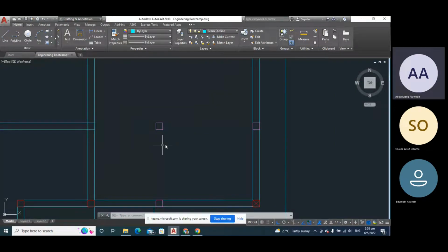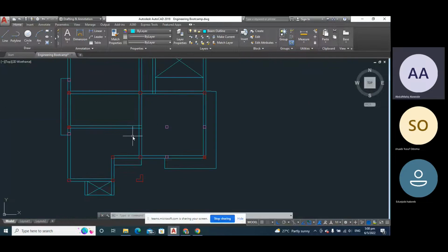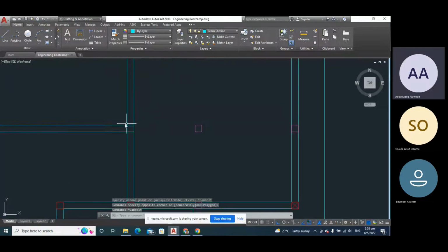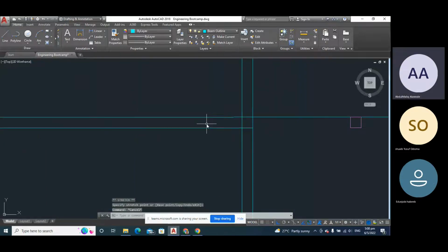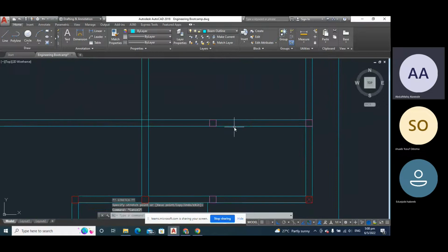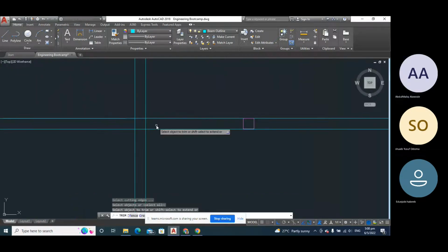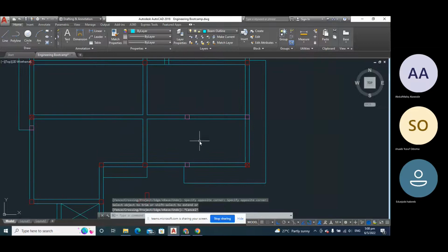This is on the slab. You understand? So on that note, we are going to edit our first floor GA. We are going to extend this beam, because we are not going to plant our column on the slab. Do you get that? Yeah.